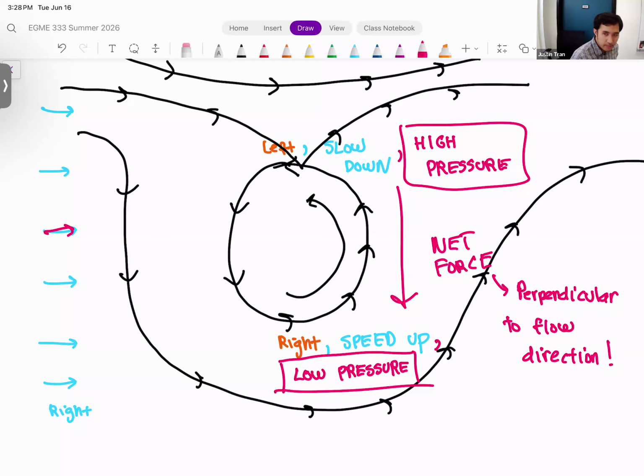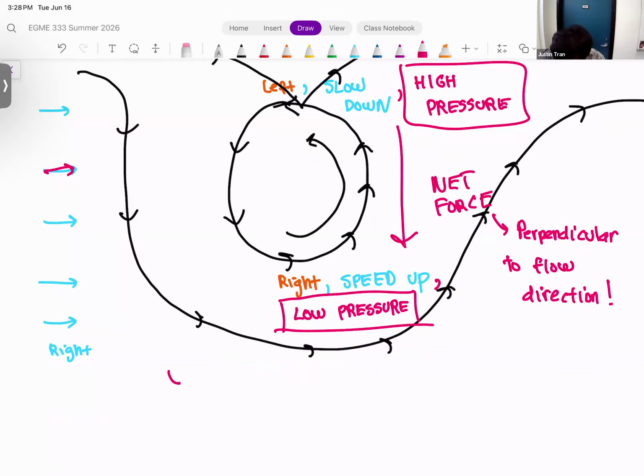And by inducing the spin, it causes the ball to either rise or fall, mostly fall, in an interesting way to fool the batter. Okay. And so this is the origin of that, or how that actually works. By introducing the spin, you literally change the fluid dynamics of the airflow around the ball, which causes this net force to make the ball rise or sink as you want. Okay, so this effect right here, right? This effect is known as the Magnus effect.